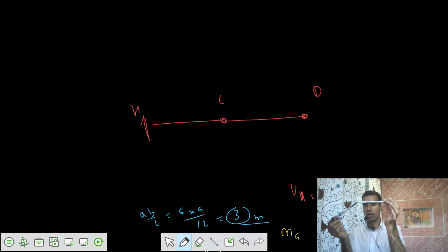This is our goal here. This is what we are saying. So this is the variation, not in this fashion, not some bent shape, we say it would be in this fashion. You can verify that if you apply a summation of that free body diagram, summation SFD, whatever you do, you can get the variation as this one, similar to that of a cantilever with an internal hinge.